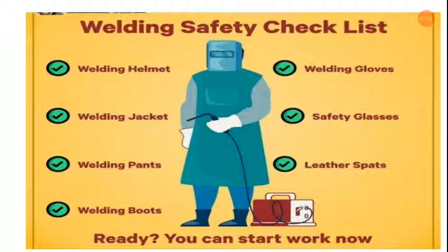A stick electrode is always electrically hot when the welder is on. Treat it with respect. If a shock is experienced, think of it as a warning. Check equipment, work habits, and work area to determine what is wrong before continuing to weld.